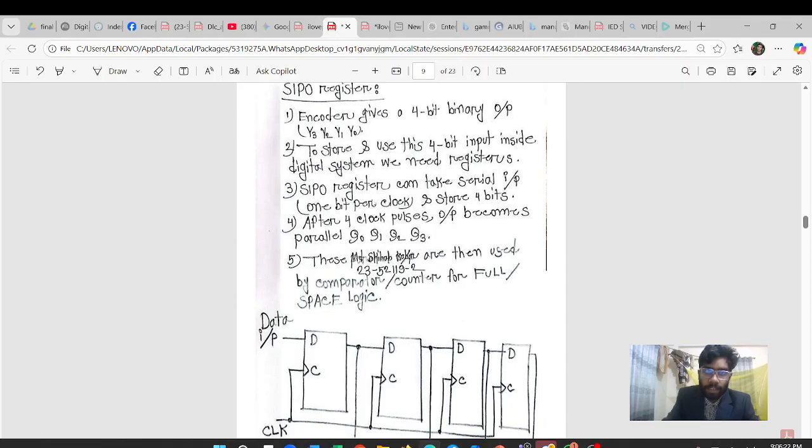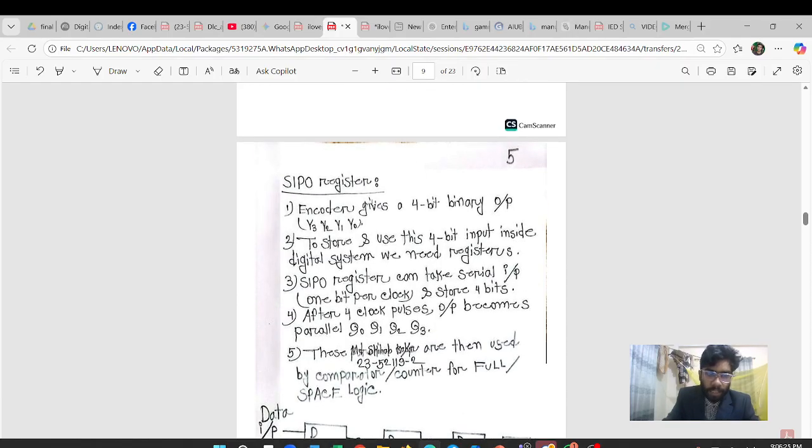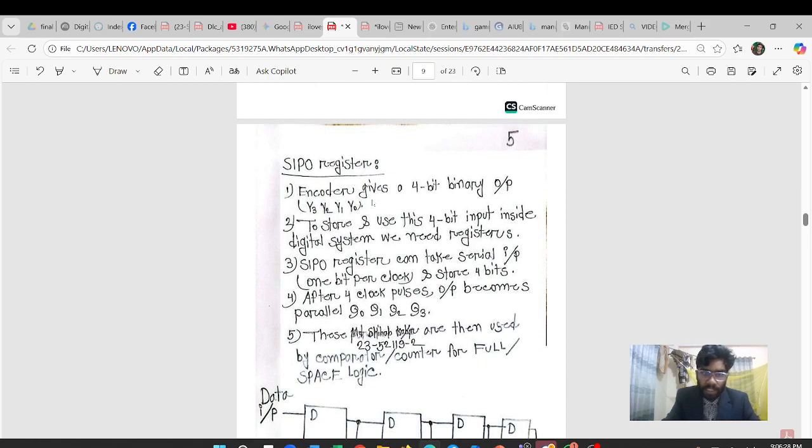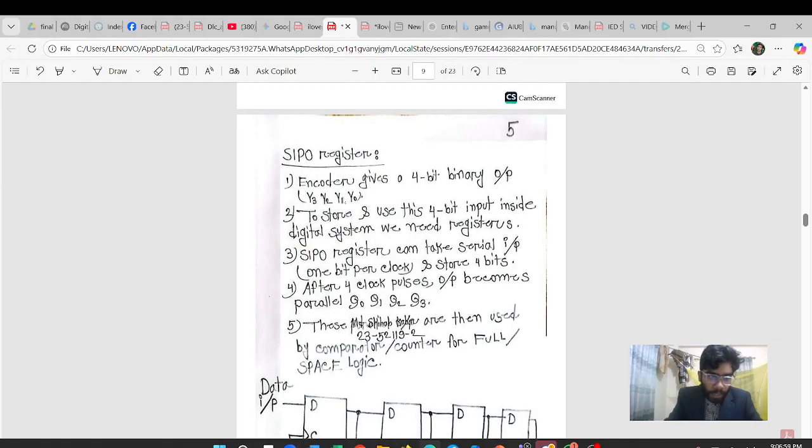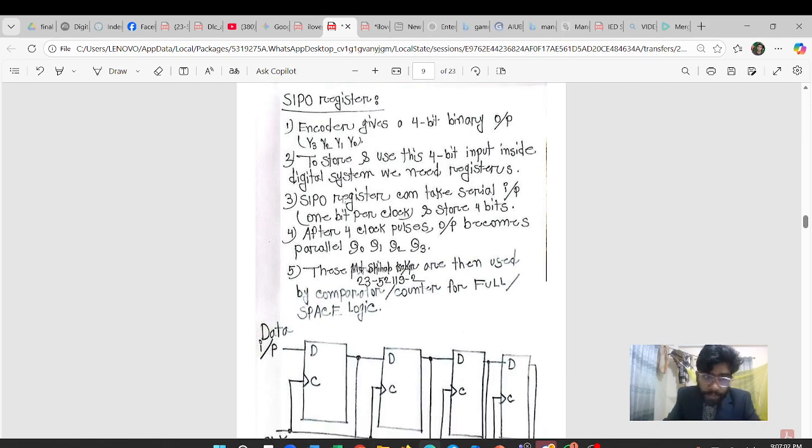Now I use a register, a SIPO register, that means serial input, parallel output. The data enters one bit at a time serially and is shifted into the register by a clock pulse. Here my goal is that once all bits are shifted in, they are available in parallel on 4 output lines. This provides a constant reference value.